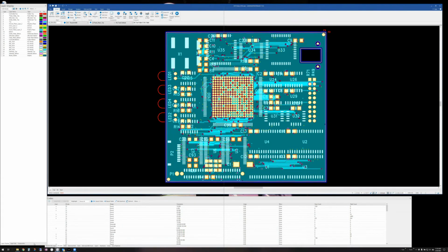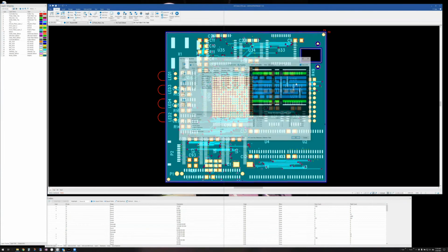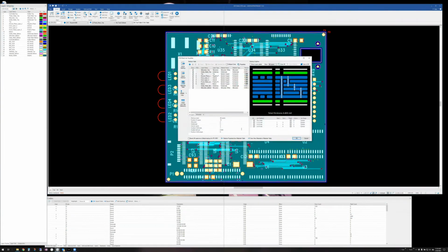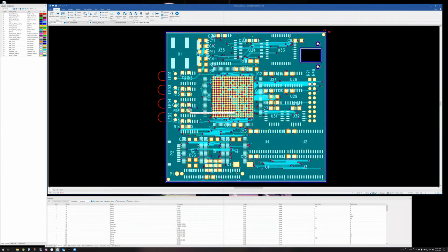You notice all the layers are defined. And if I go to layer sets, you'll see they're defined. If I go to the stack up visualizer, you'll see that it shows which layers the drills go through and so forth. So that's the advantage to intelligent data. And when I say intelligent data, I mean ODB++, IPC 2581 versus Gerber data, which is just XY coordinates and shapes.